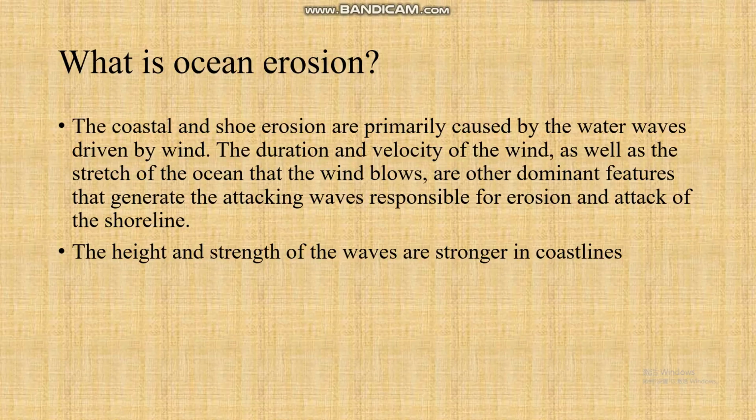So ocean erosion is the coastal and shore erosion primarily caused by the water waves driven by winds. So duration and the velocity of the winds as well as the stretch of the ocean that the wind blows are the dominant features that generate the attacking waves responsible for erosion and attack of the shoreline. So the height and the strength of the wave are stronger in coastlines.